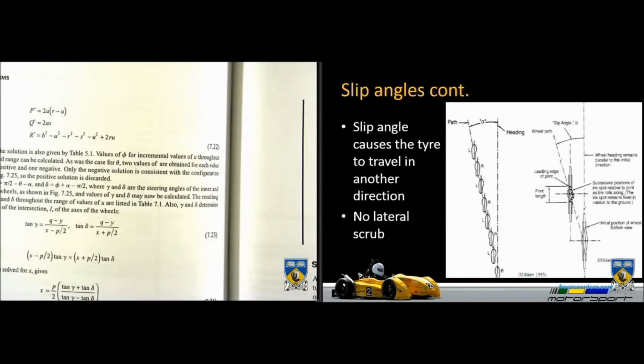So another good way to think of it is a footprint model. So if you've got your tyre slipping out with each one of these, as it rotates around, it's not actually scrubbing across the road, it's actually stepping out smoothly. The image on your right from Milliken again is a physical test they did. I can't remember when it was. This was 1800 sort of thing. It's a thin disc of rubber clamped behind 2 steel discs, and that's where they came up with the footprint model, because they found that when they twist it, it's not scrubbing, it's not scratching the surface, it's actually leaving footprints across the direction. And the difference between that wheel plane again and the path of those footprints is your slip angle.